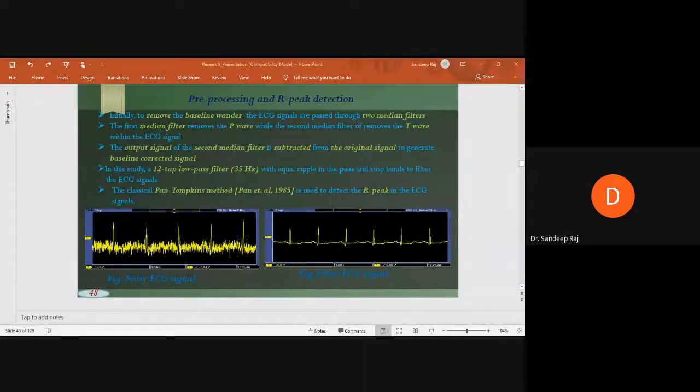And finally, we want to develop a customized hardware. So we use different components to develop a device, and this is the device that has been developed. Eagle software was used to design this 2-layer PCB, and it was designed in-house. There is a fabrication company known as PCB Power, which is based in Gujarat. We sent the design file there for the fabrication. And finally, the dimensions of the device are 90.42 mm and 60.83 mm respectively.